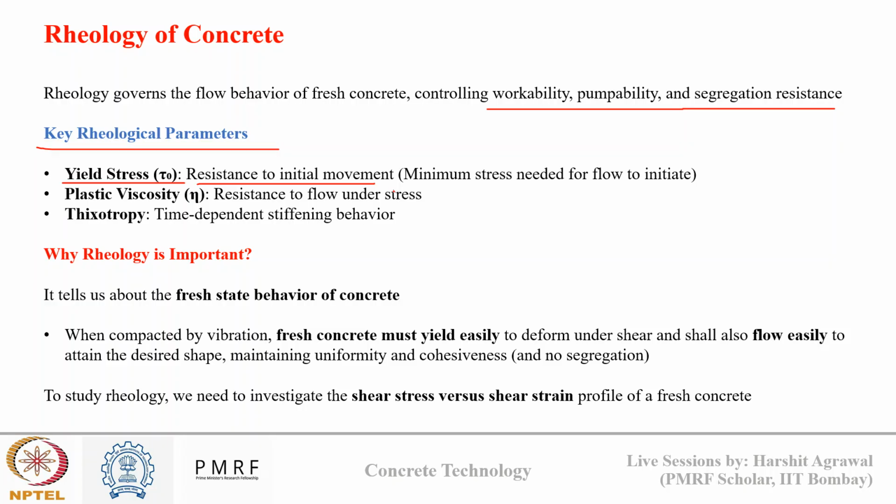Okay, so yield stress is one of the parameters of rheology. Okay, resistance to initial movement. Second is the plastic viscosity, that is resistance to flow once material has started moving. Okay, so it determines how easily concrete will flow under an applied stress.